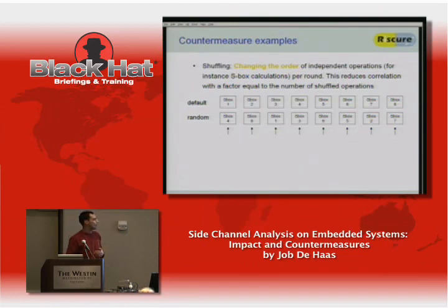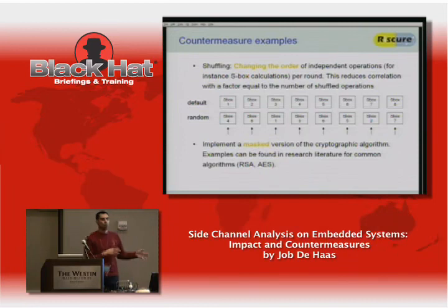So you just need to collect the same number of S-box ones again in the first row, which will happen, of course, if it's truly random. You don't have that much choice. If you want to move to a better implementation, that's not a little bit ad hoc and already proven to also leak, because it just takes more time, then you really need to move towards things like masked implementations. And this is also what we see now in modern smart cards, that AES and DES engines are using masked implementations to also make it more difficult to find that correlation point. Although they are still there.